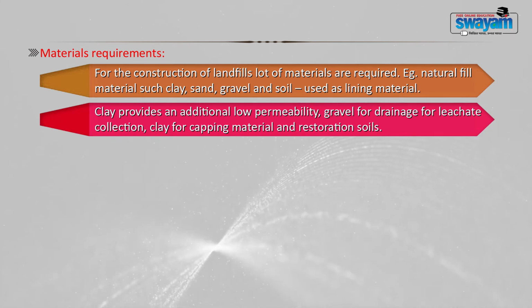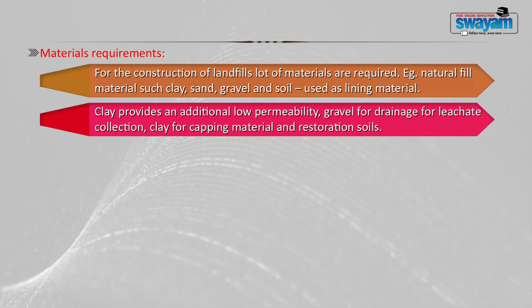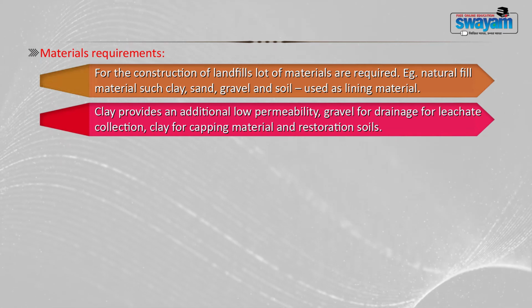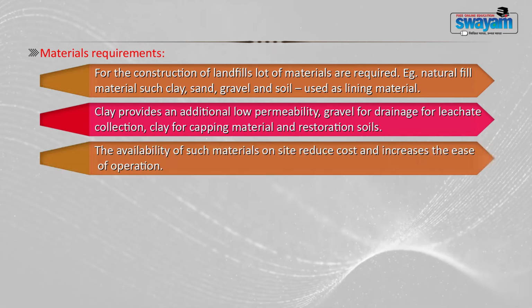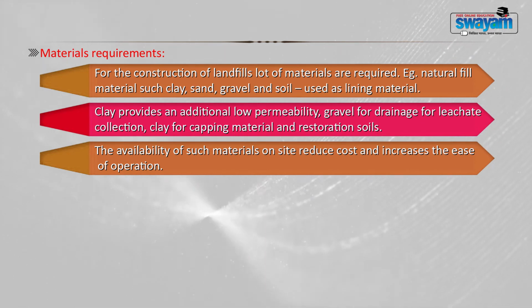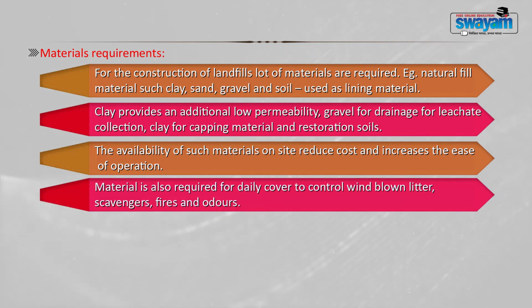So, wherever you select a site for constructing a landfill, you should see whether the land or the site itself has these materials, or at least they should be available in the close vicinity. Now, if these materials are available near the site, it will reduce the cost and increase the ease of operation. The material is also required for daily cover to control wind blown litter, scavengers, fire and odor.